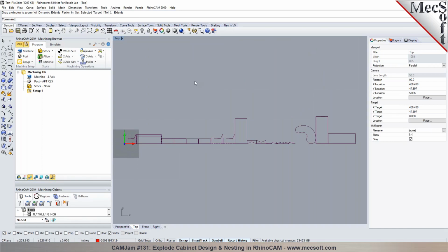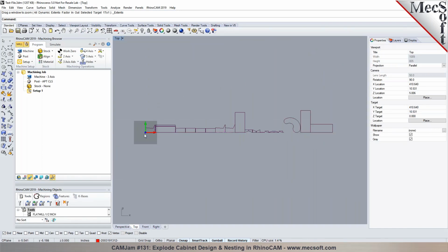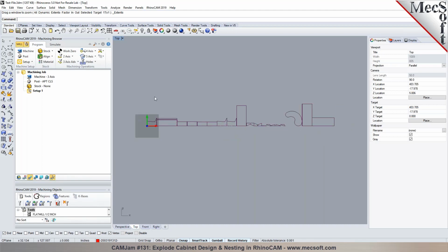Will it scale it down for me? Because I need it on a 24 by 36, and obviously this scale is 1:1. Okay, so you want to scale all of these parts to a smaller size? Yeah, because it needs to fit in the laser cutter first. Okay, so what you would do is use the scaling in Rhino. You can basically scale it by the ratio you want.